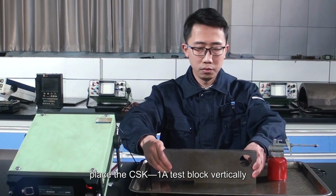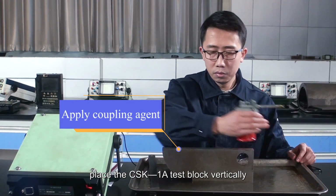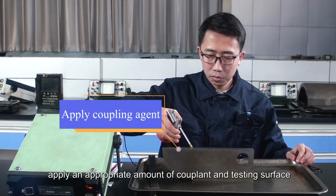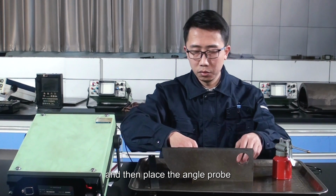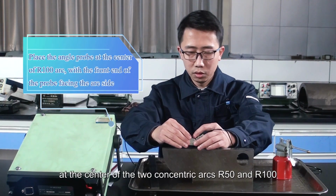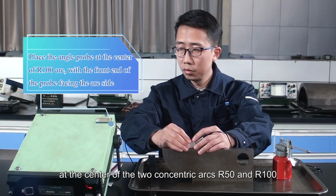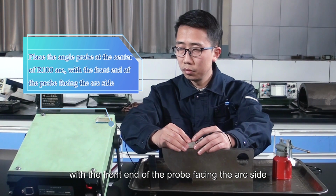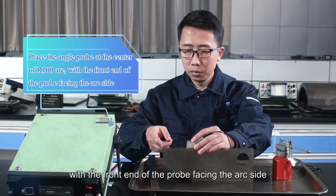Place the CSK-1A test block vertically, apply an appropriate amount of couplant to the testing surface, and then place the angle probe at the center of the two concentric arcs R50 and R100, with the front end of the probe facing the arc side.